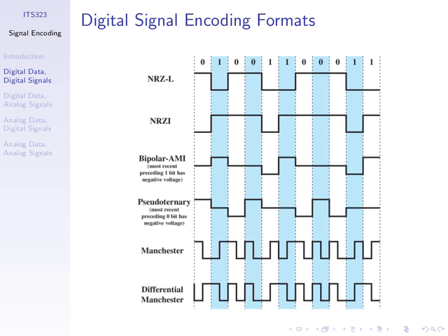If we had Manchester encoding with all zeros, it would look like this. If we had non-return to zero, it would look like this. The receiver can use this change to indicate, okay, this must be a new bit. If we changed here, a new bit has arrived. Here, when does a new bit arrive? It cannot detect any information from this case. So one advantage of some of the encoding schemes is that it can help the receiver to synchronize its clock with the transmitter.